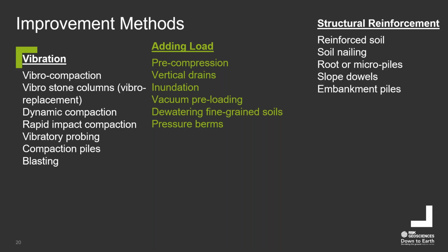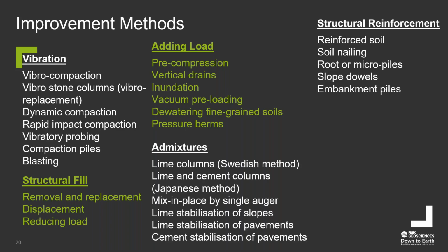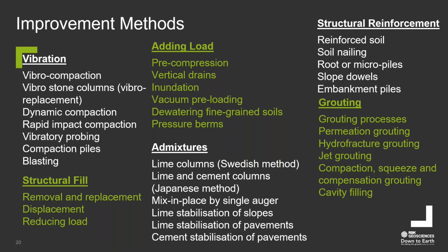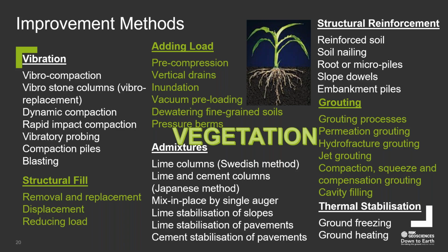Structure reinforcement, again, you can just read through those. I'm not going to read them all out because of the space I've got available today, but I'm just trying to show there's a huge range of techniques that can be used. Structural fills, admixtures, including the stabilizations using lime and cement. Grouting techniques, both in terms of permeation grouting, compaction, compensation grouting, and then thermal stabilization, as well as ground heating. You can use ground freezing, but that might be to immobilize groundwater inflow into excavation trenches. One final technique by way of sort of vegetation is to try and gel everything together, shall we say.